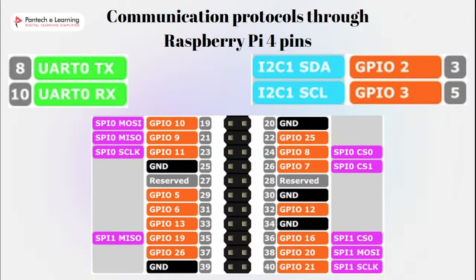So when to use I2C versus SPI on your Raspberry Pi 4, right? Well, the answer is quite simple. Sometimes you will find a sensor that is only I2C or SPI compatible, and sometimes you will just want to have a balance between those protocols. For example, you will choose to use I2C if you already have many components using SPI. As you progress, you will start to know the difference better. But for now, let's keep things simple.